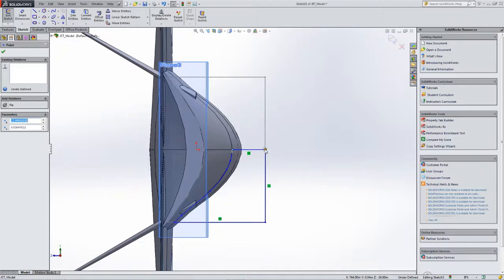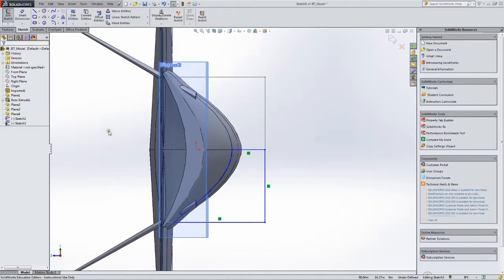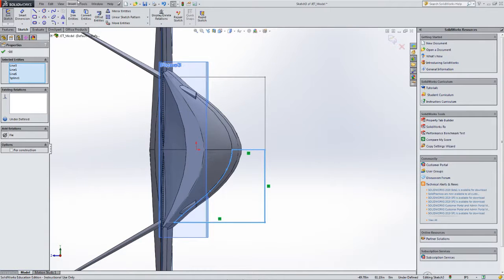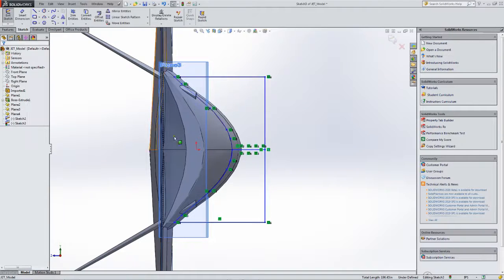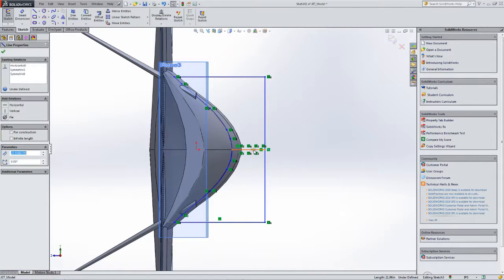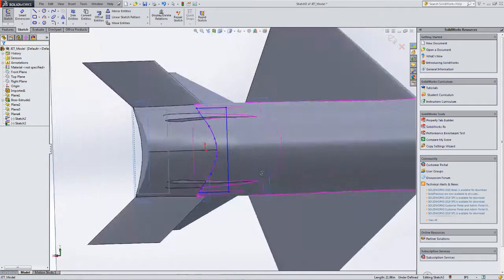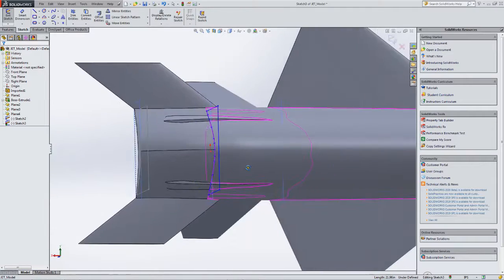But normally when you do, it will automatically stop drawing. Okay, the point is no longer at 0, so I put in 0. I've got the parallel, so this one will be at 0 too. Very important that you do that before you mirror. Okay, highlight the whole thing, mirror entities, mirror about this point, green checkbox, delete the mirror line, and we've got our second profile for deleting that vertical tail.